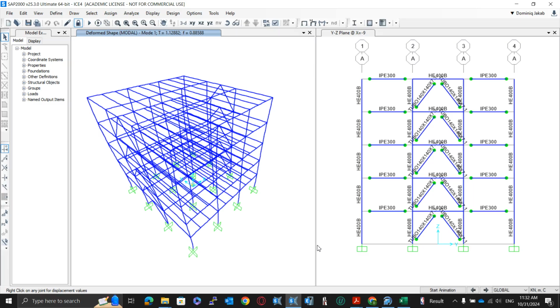Because we cannot satisfy the lateral displacement, so we need elements to make it stiffer such that the displacements are smaller. So the braced frame, it doesn't matter if it's X frame or V braced, we do not go into types of braces, but generally the braced frame is much more rigid compared to the moment resisting frame. And the eccentrically braced frame is in between. Now, given these facts, I'm asking again, is the behavior proper or not?